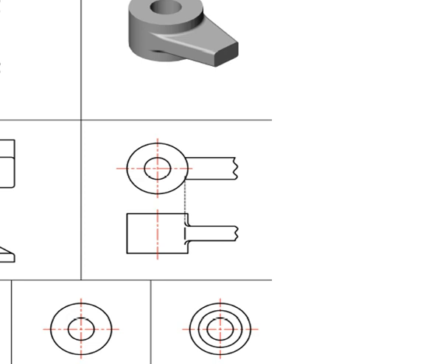With this one, there isn't a change in plane between this flat piece and the cylinder. It's a nice and smooth, gradual transition. So then we don't show a change in plane. With this one, there is a change in plane from this straight portion in the top view to the circle. So for this one, you will show the change in plane with that little line.